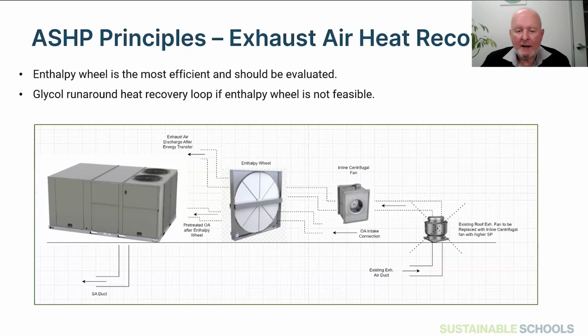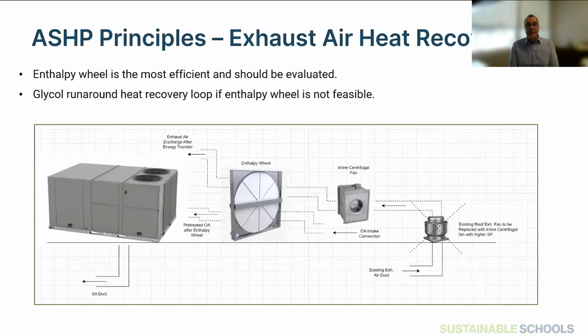Now, remind me, Paul, have you typically been specifying exhaust heat recovery on those units? Yes, they all have enthalpy wheels for sure. And the areas of the school that are served by the VRF technology have a standalone dedicated outdoor air unit. We're finding it's not equipped with heat, so it's just recovering exhaust temperature. And on recent -20 days, we're seeing a supply temperature in that unit of right around 12 degrees Celsius. So it's amazing that we can provide that without any heat at all. That's great.